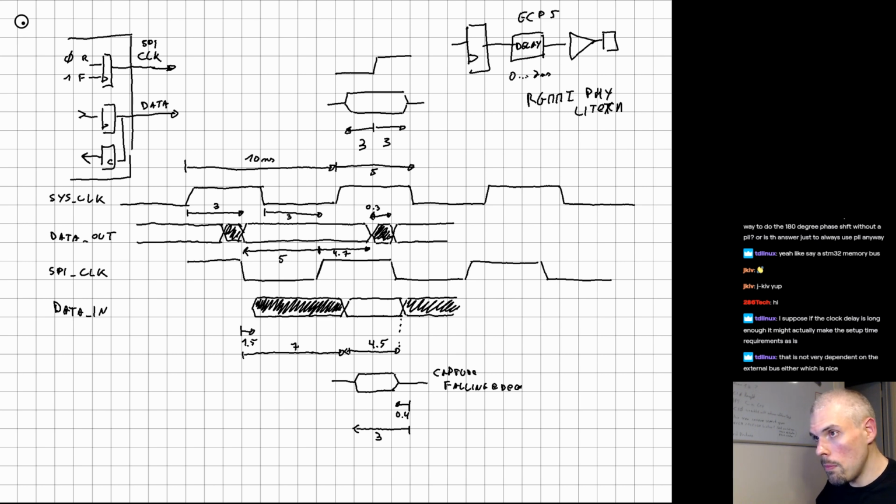The first one is that some FPGAs have programmable output delay between the IO register and the actual pad. Well, you have that the other way around as well. You can delay the data from the pad to the IO register through a programmable delay. Again, not an option in the iCE40, but on the ECP5, on Xilinx 7 series, that definitely exists, and that's a perfectly valid option to use.